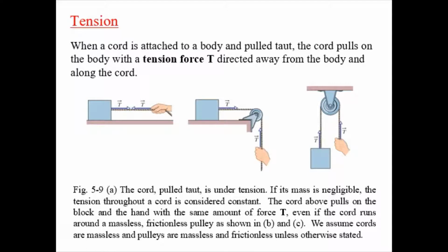Mainly, to get the direction of a tension force in a cord, I usually ask myself, if the cord was snipped at that location, what direction would the object I'm interested in go, or what would happen? That tells me what direction the tension force is.